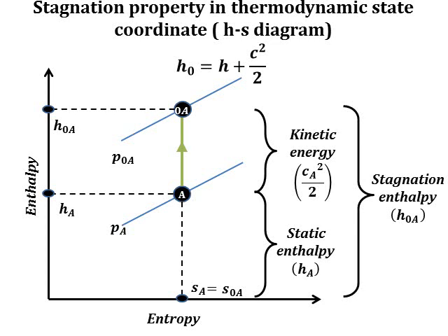That means for low velocities, that is for subsonic flow, the distance between the static condition and stagnation condition will be less because the velocity is less, thereby the kinetic energy is less. Whereas in the case of supersonic flows, which are high speed flows, the kinetic energy component will be very high, because of which the static point A will lie further away from the stagnation point 0A.